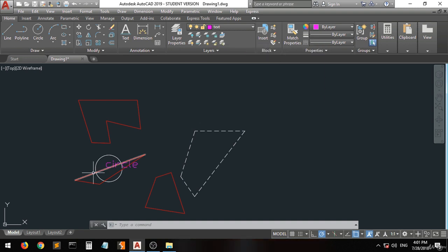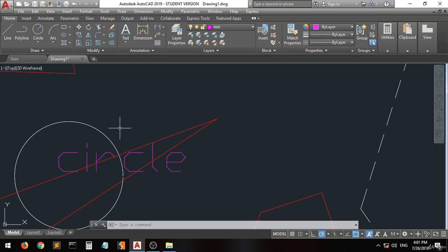What if you want to work on small details, but you want all the objects to be shown for you, because this little bit of modification will be connected to each other? So you want all the objects to be shown, but you don't want to modify them. So what to do? You go to something which is called lock. For example, I want to modify this line, but I don't want this circle and this text here to be modified. So I go to something called lock.